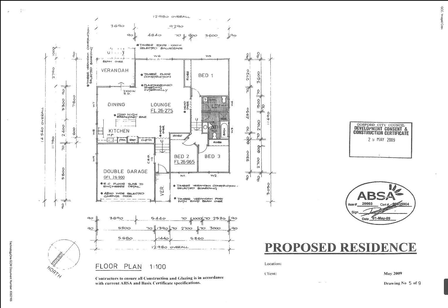Bathrooms, laundries and kitchens are usually easy to spot on most projects. The laundries and bathrooms in particular have always shown with floor tiles hatched. And in here we've got the laundry, the laundry tubs, a washing machine and a toilet. Toilets might have the letters WC for water closet or LDS for low down suite. All in all, it's still a toilet.